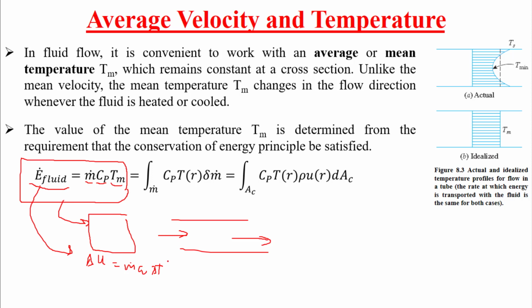Okay. And if we are talking about a system that has inlet mass and outlet mass, then E dot will equal H, and this is equal to m dot Cp delta T. So here, I think you guessed that this energy, we mean that we are calculating the enthalpy, which is equal to m dot Cp delta T, or T mean.